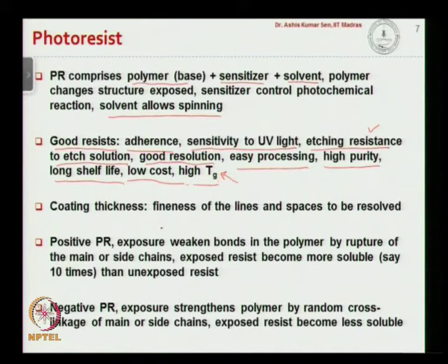The coating thickness many times is going to affect the fineness of the lines or the spaces to be resolved. So we would have the precision of the photolithography using the photoresist.